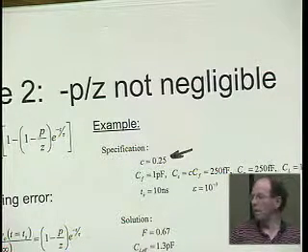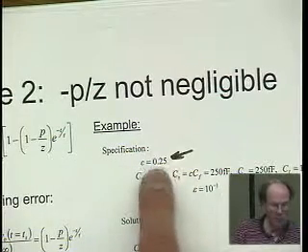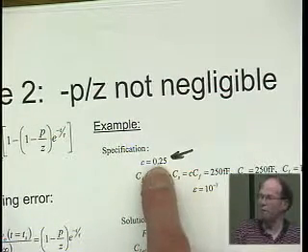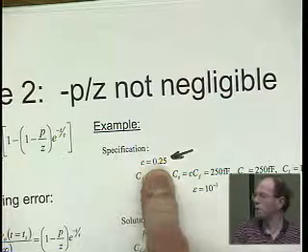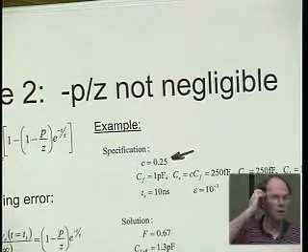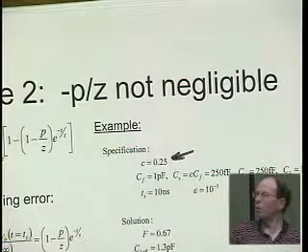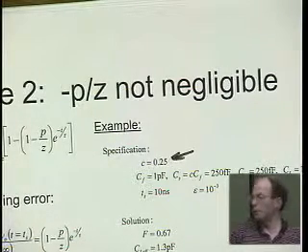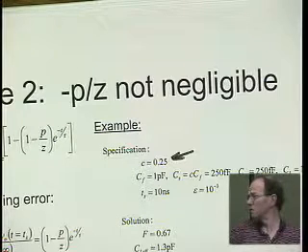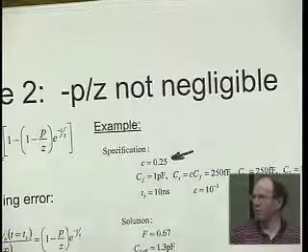A very common application where we need gains of less than unity all over is in sigma delta A to D converters. There we have a chain of integrators, and invariably the signal keeps growing, which is a big problem. So usually these integrators have a gain like a fourth, a fifth or so. That really happens.